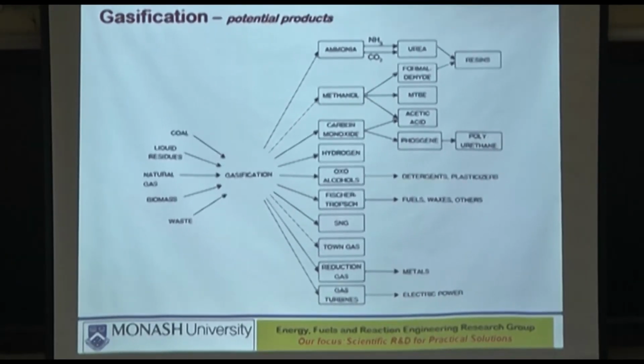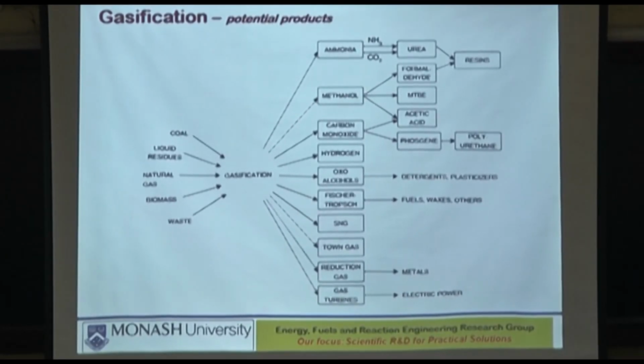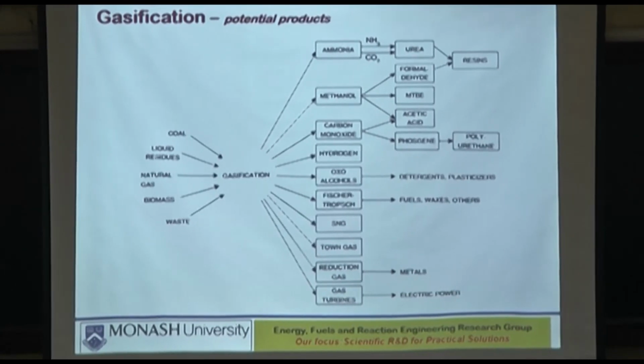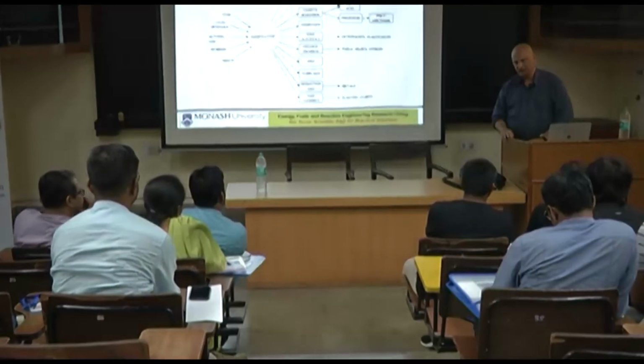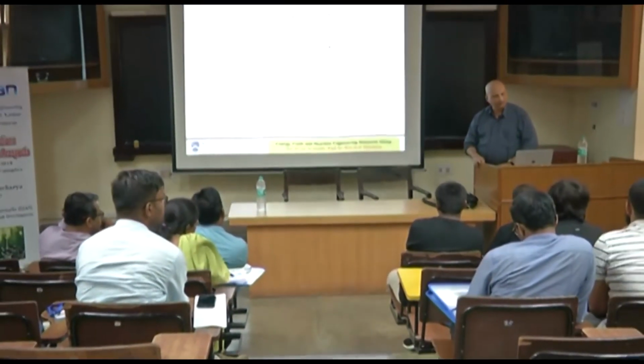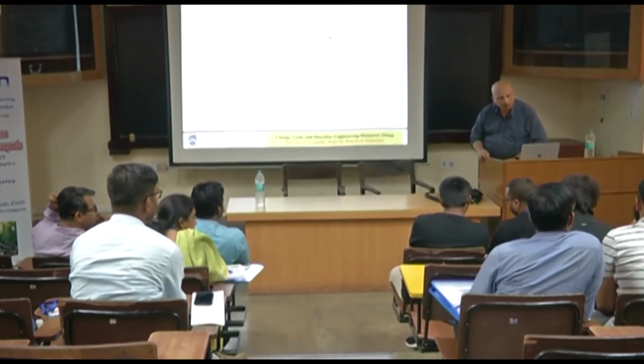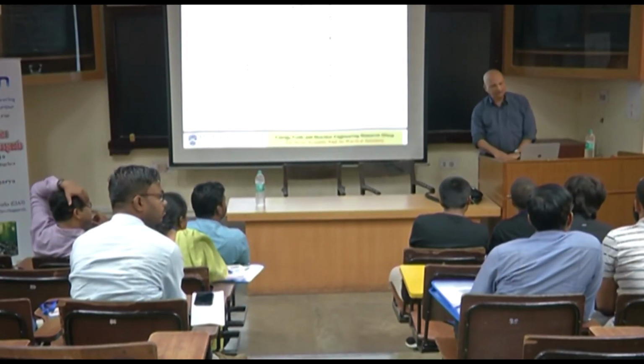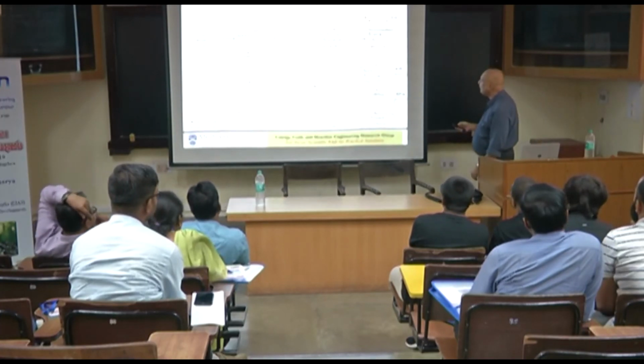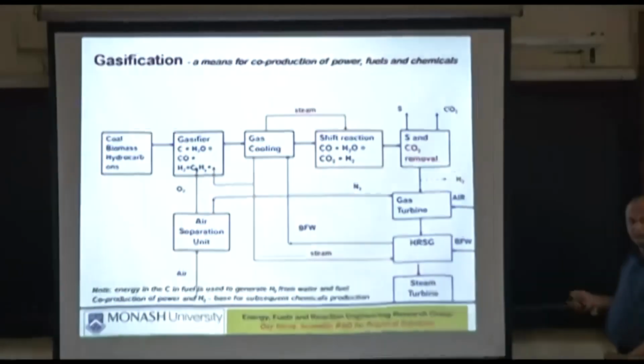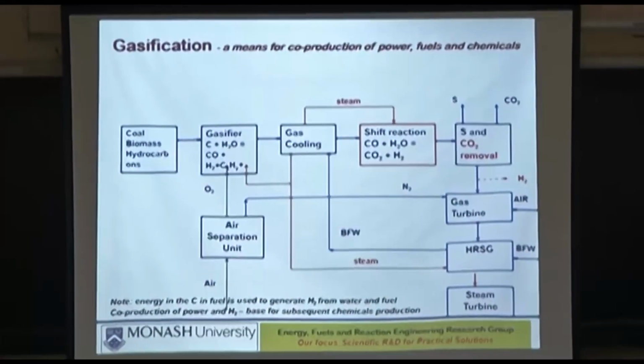Not separated directly, not separated at the gasifier at all, after cooling and all. Gas separation at high temperature is an unfinished, unresolved business. If you want to, membrane. That's the best. What should be the temperature of the gas after the gas cooler? You mean here? Whatever temperature you want to run the shift reactor at.